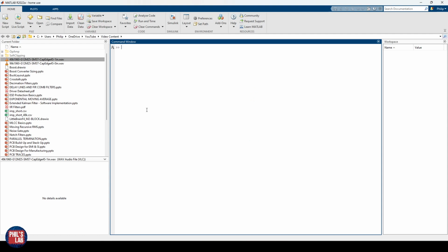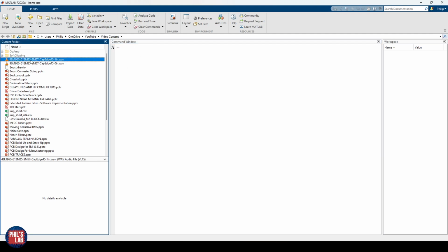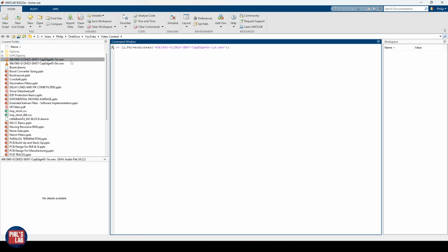And the way we can do that is plot this impulse response magnitude versus time. So I'm in MATLAB now because this just lets me very easily visualize an impulse response, but you can do this in Python or any language as well. So I have one sample loaded in, an impulse response at 48K. I just picked a pretty random sample, and this is one we're going to be using throughout the rest of this video. We can load in this WAV file to an array, so just an array of floating point numbers, as well as the sampling rate using the audioread function. And then we can just plot the magnitude versus time.